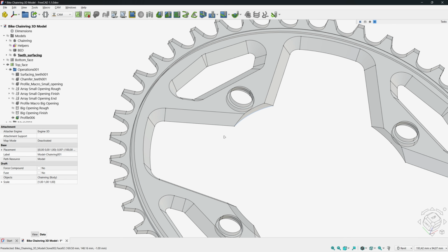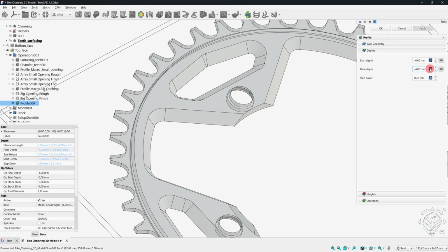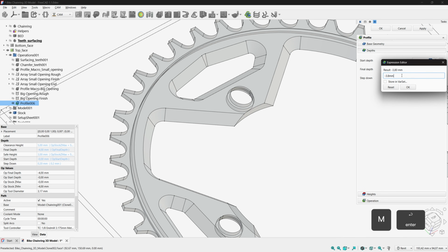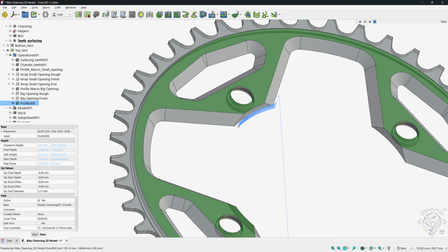And patatra, the toolpath doesn't get created. Actually, this is a bug in FreeCAD. When you ask it to make a profile on an open contour, it struggles to determine the end of the machining. To fix this, go into the Profile and in the Depth tab, set the final depth to -3.8 instead of -4. Then you can exit the operation. Now your toolpath should be created correctly.